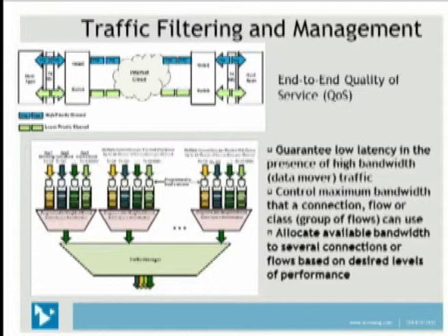Well, on this card you actually have the ability to flag certain node addresses and say that packets coming from or going to a particular node address have higher priority than others, and the lower priority information would just be let to wait a little while. And that's a great thing, because Ethernet is used more and more, not only for just data communications, but also for control.